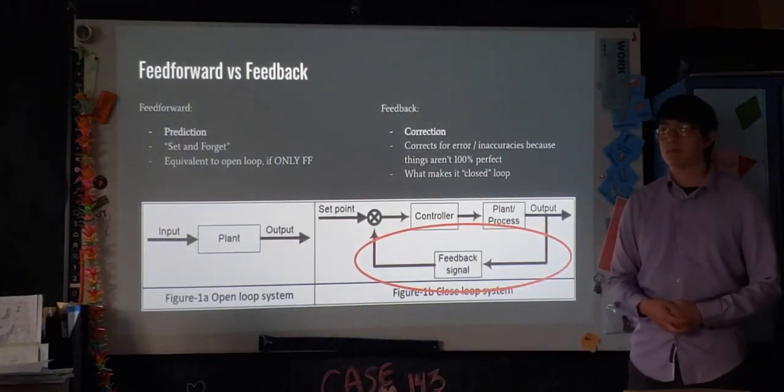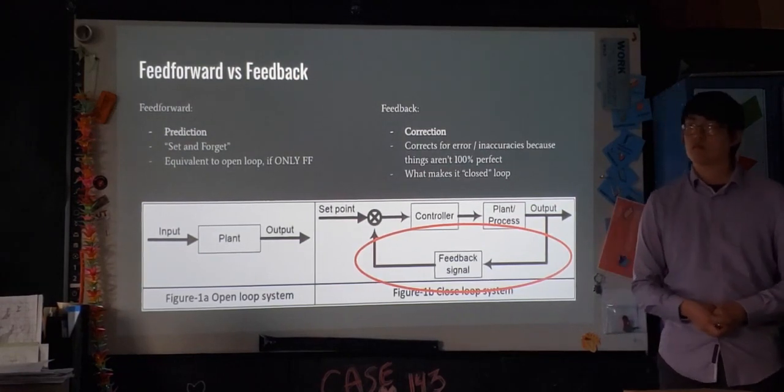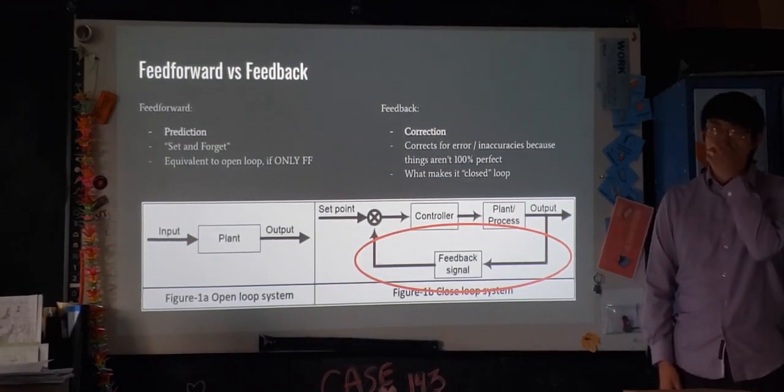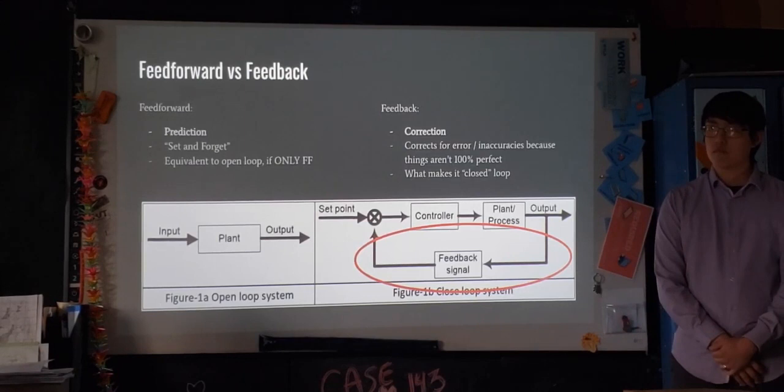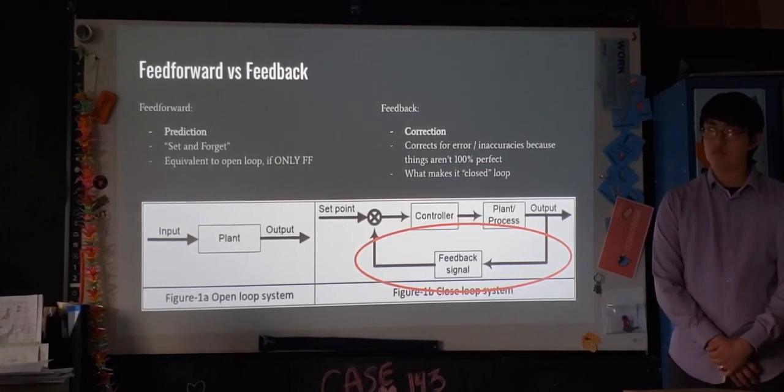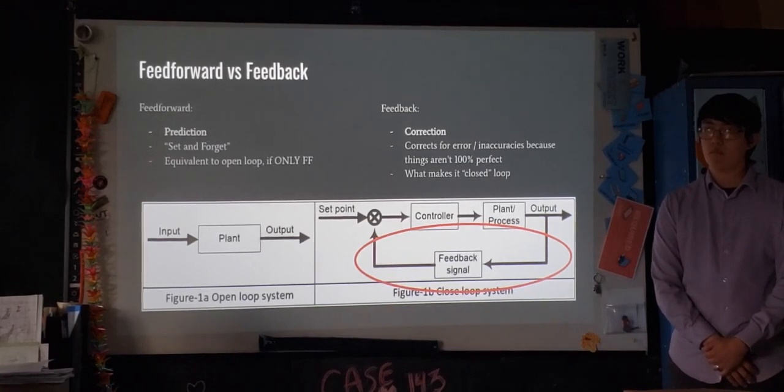Yep. So if we were doing feed forward control on, say, the robot, we would probably take measurements. If I give it 3 volts and it goes this fast, and I give it 5 volts and it goes this fast, you'd wind up with a little table, right? And then when you said go 5, we'd go look in the table and say, well, that takes 2 volts, right? But that would work only if the table was completely accurate. But every time you mess with the robot, the table gets wronger and wronger.